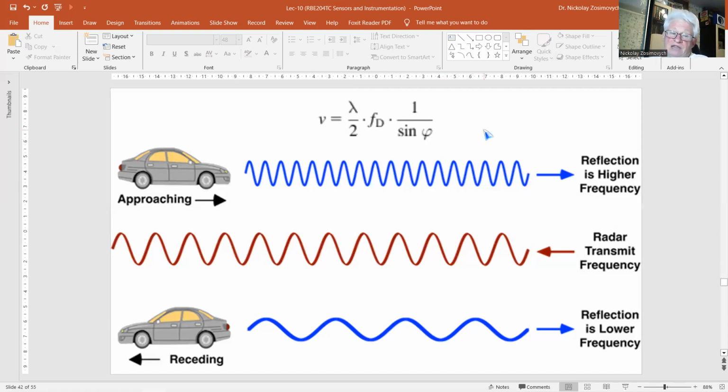These errors can largely be eliminated using a differential configuration. Two lasers are pointing to the ground with incident angles of plus minus 18 degrees with respect to the ground normal. The Doppler frequency that can be reconstructed from the two output signals is less sensitive to car movements other than in the driving direction. Experiments with the two laser configurations showed a mean standard deviation less than 0.04% at velocities up to 100 kilometers per hour.